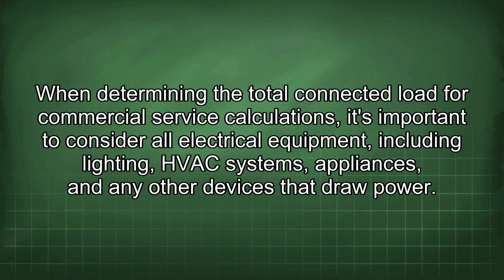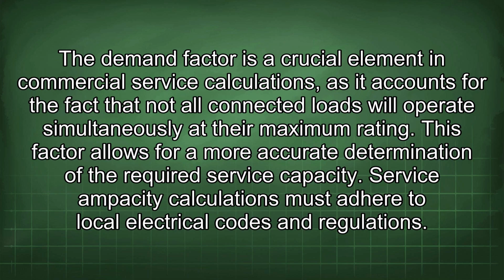When determining the total connected load for commercial service calculations, it's important to consider all electrical equipment, including lighting, HVAC systems, appliances, and any other devices that draw power. The demand factor is a crucial element in commercial service calculations, as it accounts for the fact that not all connected loads will operate simultaneously at their maximum rating. This factor allows for a more accurate determination of the required service capacity.